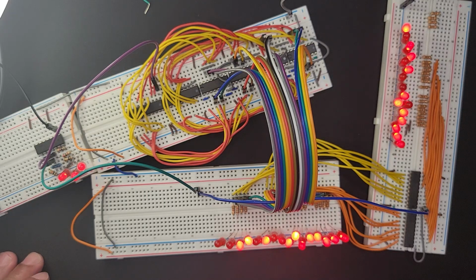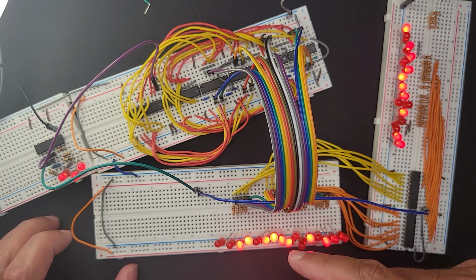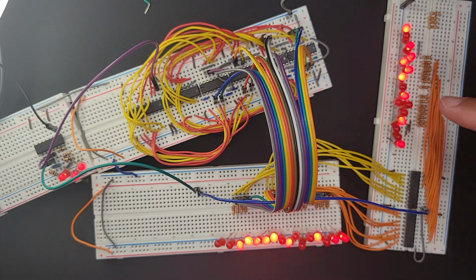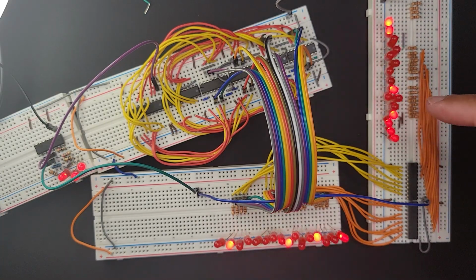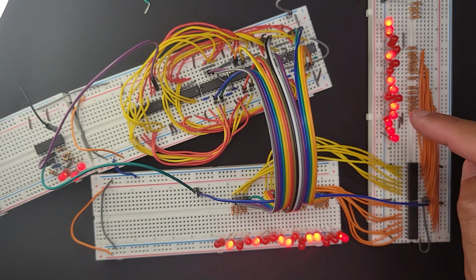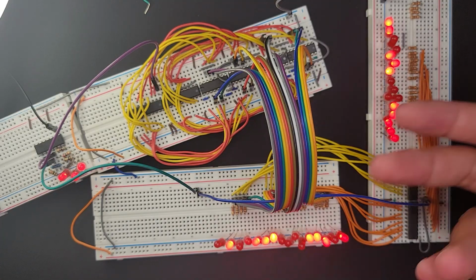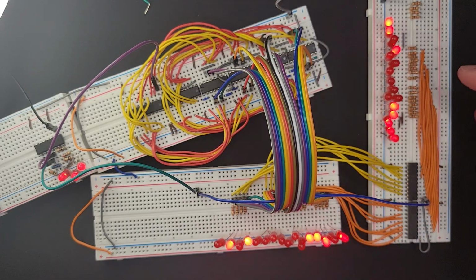looks beautiful. So we have our instruction pointer here incrementing, and we have our instruction memory address register, the IMAR, who is going to be responsible for pulling the instruction from the RAM. So next up, we need to get the RAM working so that we can draw this address from the RAM. And then we'll end up having to put an instruction register where we put that instruction and we can get